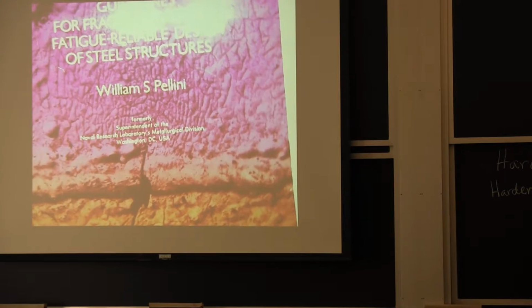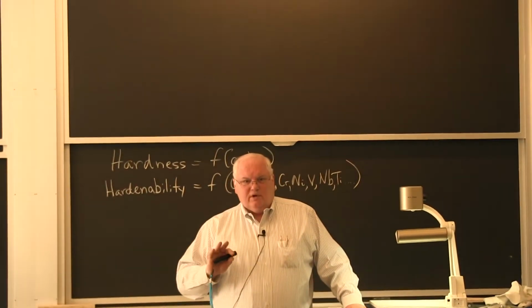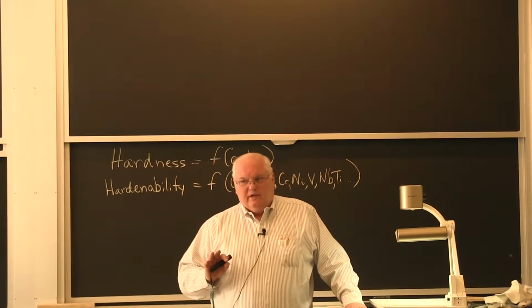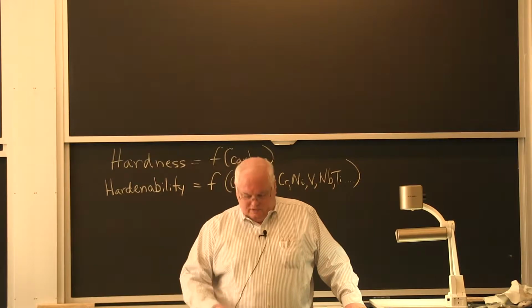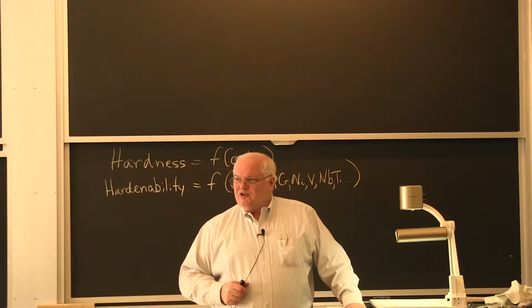So arc strikes may be cosmetically unappealing, but they can actually be harmful, and so many of the codes will require that you grind off the arc strikes, okay? And you don't like welders who go around hitting the electrode where they're not supposed to when the lights aren't on, okay?